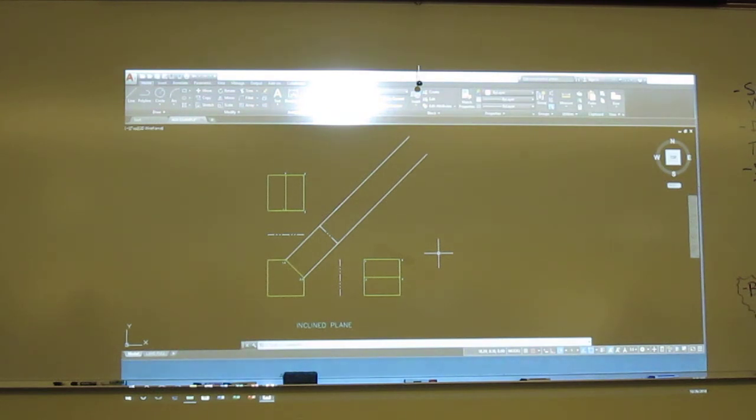Yeah, good, it should be, so just move it. No, just move it. Just do a move. Move on that line. Okay. Now just move that one. Do that. Yeah. Now just use endpoint to endpoint. You can use grips, just grab your grip right there. Click on that grip, now use your space bar to go into the move command. Use your endpoints. Okay.